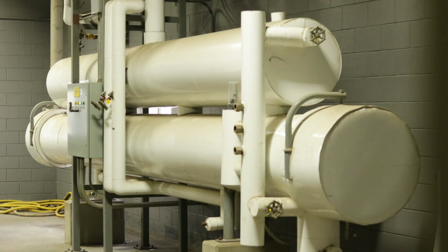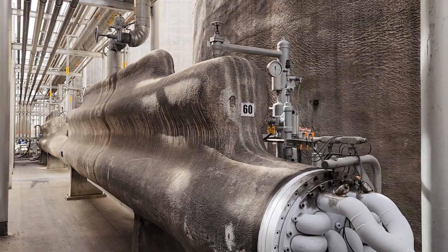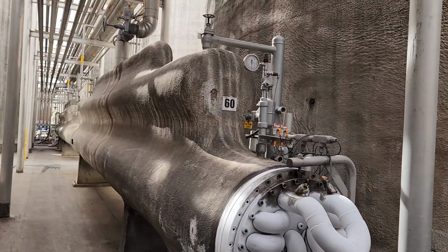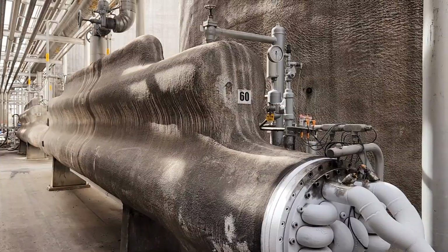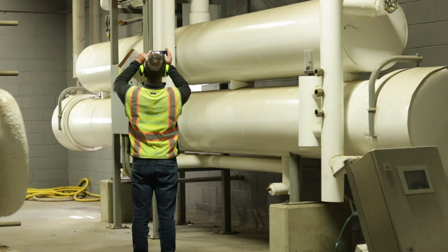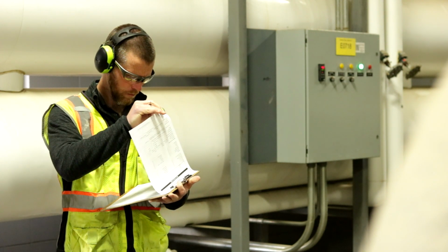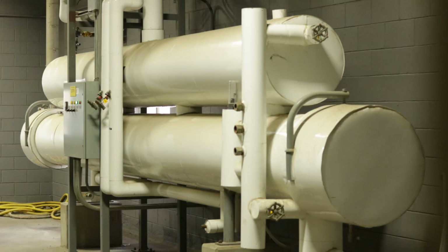Shell and tube heat exchangers are widely used in the wine and other beverage industries. One advantage of shell and tube heat exchangers is that most tubes are large enough to accommodate high fluid flow rates and will not be affected by small solid materials such as pulp or grape skins that have not been filtered out. A downside of shell and tube heat exchangers is that they are typically very large, taking up valuable real estate at a refrigeration facility.